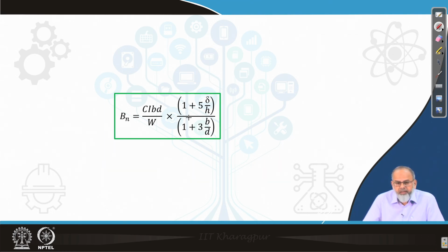number, and of course, tractive efficiency, which is the ratio of coefficient of traction to coefficient of gross traction, is also a function of mobility number. Hence, instead of calculating rolling resistance or coefficient of traction or tractive efficiency, what we have to do is simply calculate the mobility number and then compare the mobility number of a single tire with a dual tire.